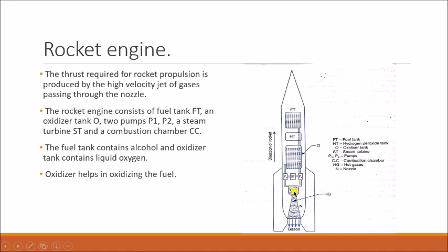The hot gas produced in the combustion chamber is permitted to escape through an opening, and then through a diverging expansion nozzle. You can see the expansion nozzle here. The pressure and temperature produced are passed through this nozzle, and sufficient pressure is provided so the nozzle chokes and a supersonic jet is formed.